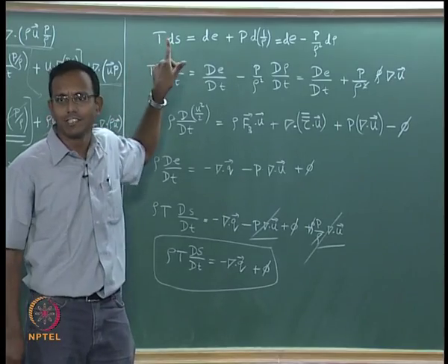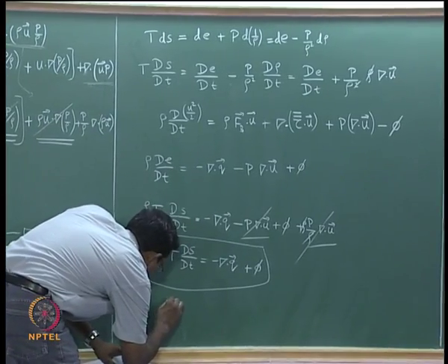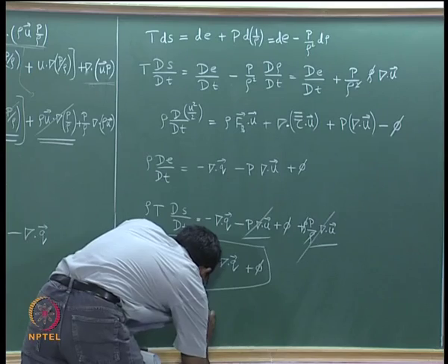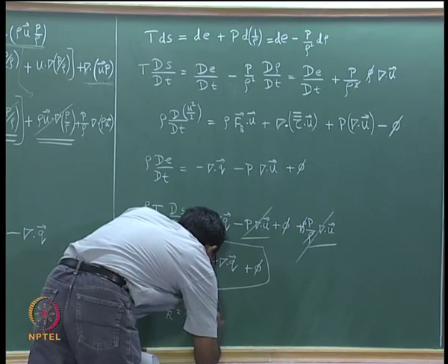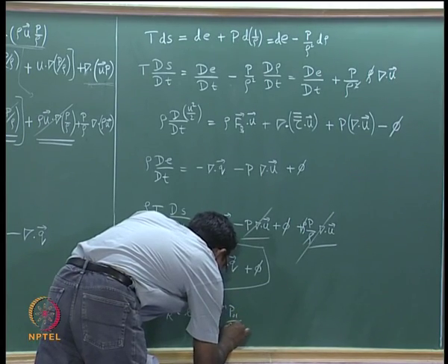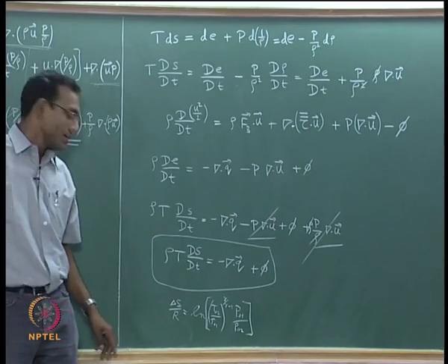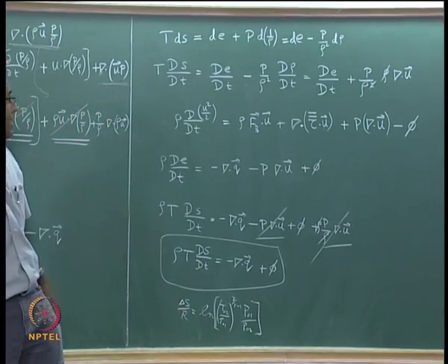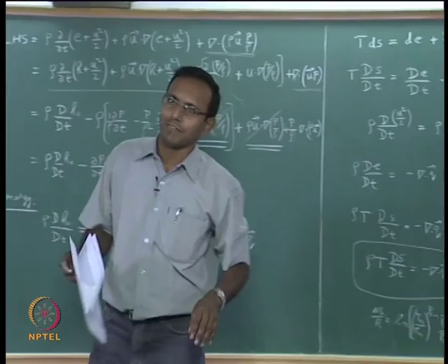Okay. If I expand it, we did this long back. I do not know where I have that expression right now, but we found that delta S by R was equal to log of T02 by T01 to the power gamma by gamma minus 1 multiplied by P01 by P02. We had one such expression. Okay. This is going to take care of that fluid mechanical way of increasing entropy. Okay. This is one more form of writing it. This is actually derived from this top equation. We won't go into the details of that right now. It was done, I believe, just after the moving shocks discussion.